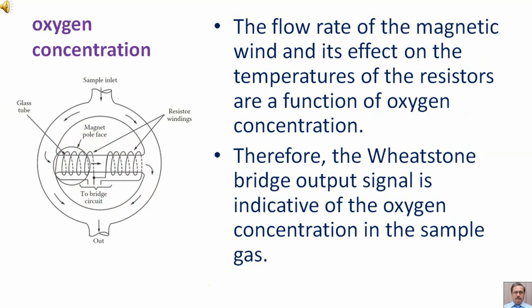The flow rate of the magnetic wind and its effect on the temperatures of the resistors are a function of oxygen concentration. Therefore, the Wheatstone bridge output signal is indicative of the oxygen concentration in the sample gas.